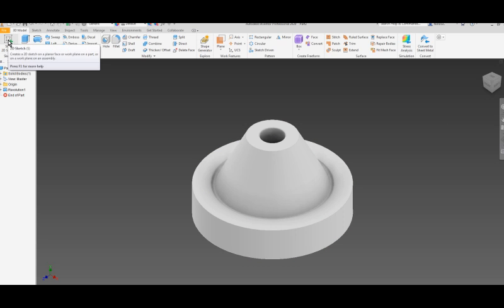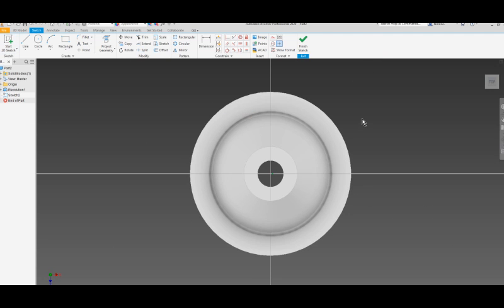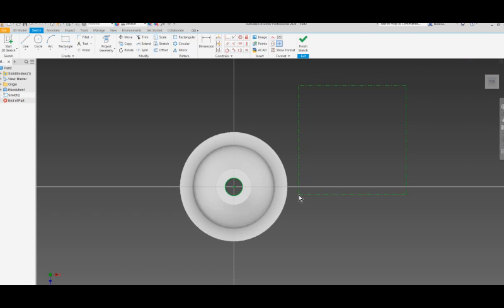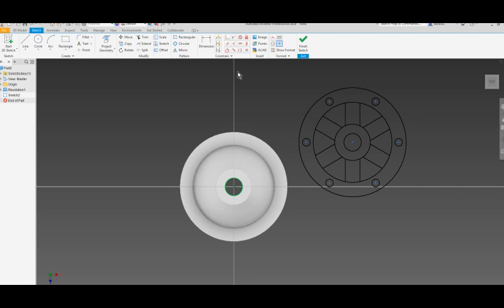Alright, I'm going to click on Start a 2D Sketch. I'm going to select this surface this time. Let's move over here. Before I paste, I'm going to project, say, the circle so I have the exact center, which is right there. Let's go right mouse button, paste, find a location. Doesn't matter where, say about here, left click, and there is the top.